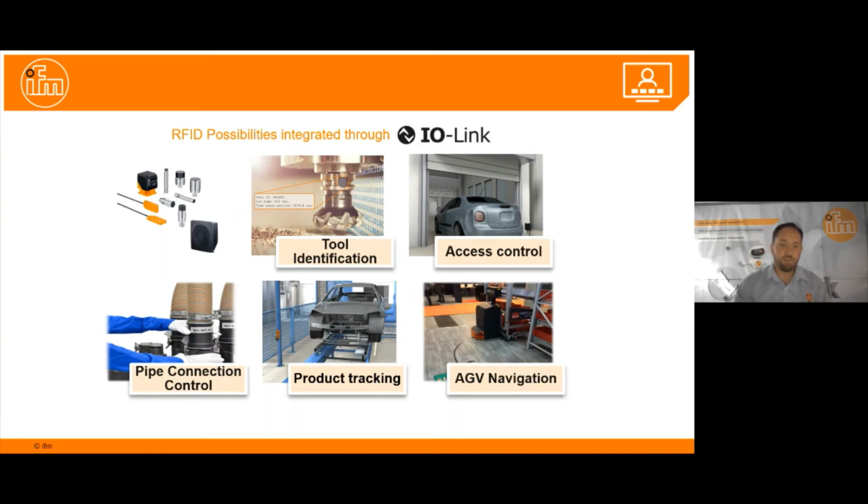And if we put RFID readers on either side, on the storage vessel side pipes and on the production vessel side pipes, and we give the hoses tags, then we can identify where we're pumping to and actually increase the product safety, because also there's cleaning materials at play generally in these food environments.